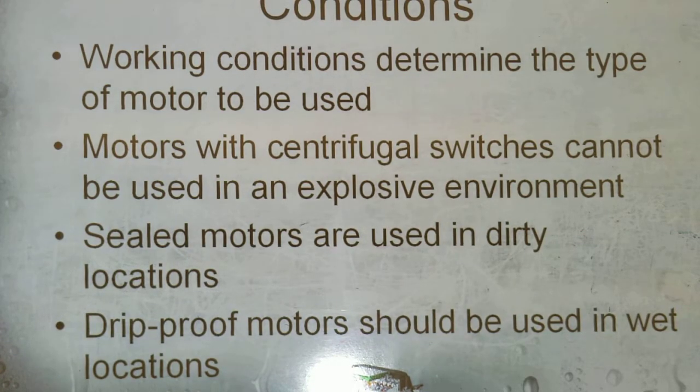Electric motor working conditions. Working conditions determine the type of motor to be used. Motors with centrifugal switches cannot be used in an explosive environment. Sealed motors are used in dirty locations. Drip-proof motors should be used in wet locations.